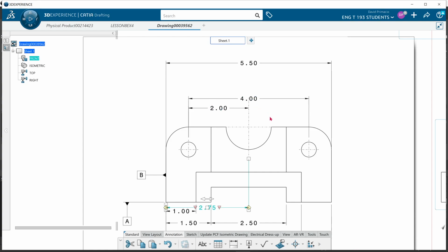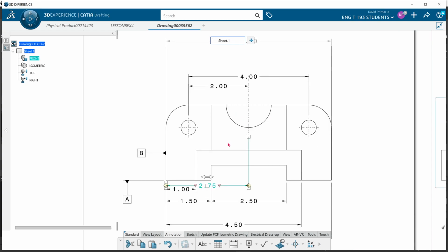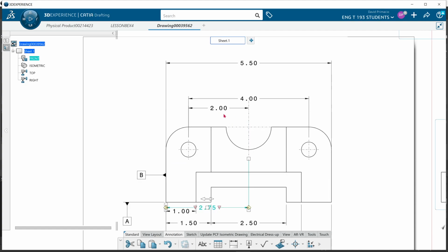All right, that's going to give me a lot better shot if both are dimensioned the same way. You're going to have a lot better chance of getting that to work out. Now I'm also going to show a different way to handle that. But for now, this is how I want you to dimension it. I want you to try and control the holes. Think about how the holes have to line up.